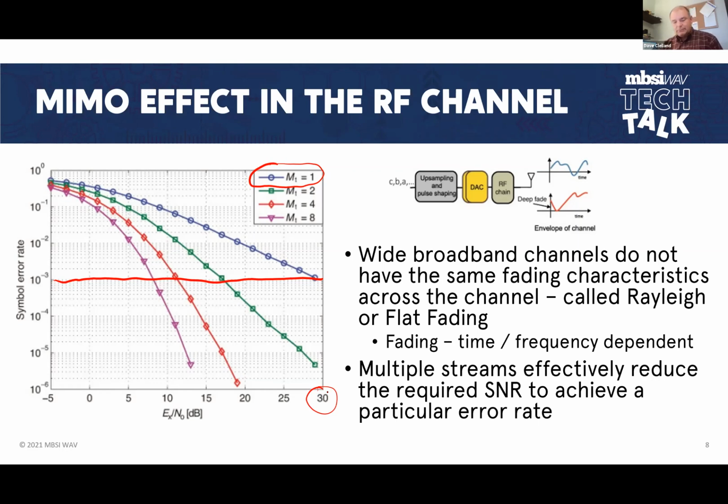That's monstrous. We know by the free space loss formula that I double my range every 6 dB. So this is double that. I need to half the range in order to maintain that on the SISO network. And we see that oftentimes. Take the old days, single channel, single in, single out radio systems.